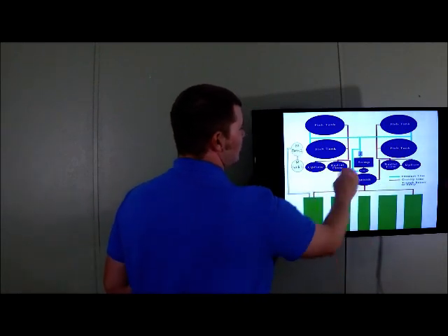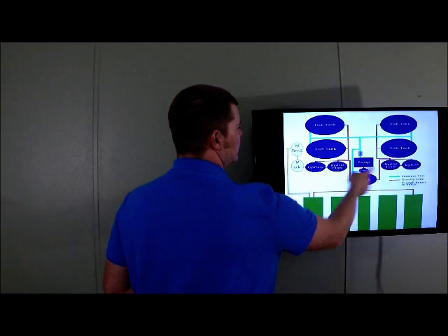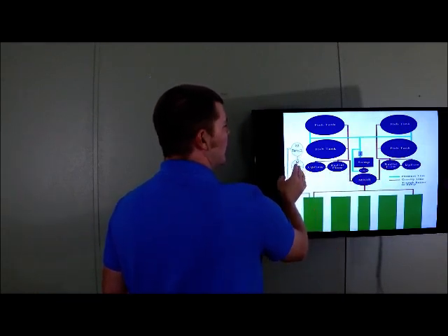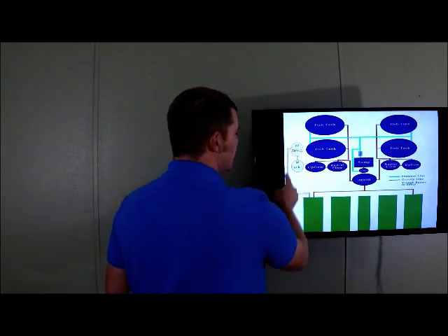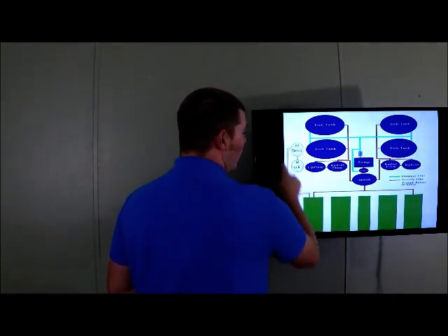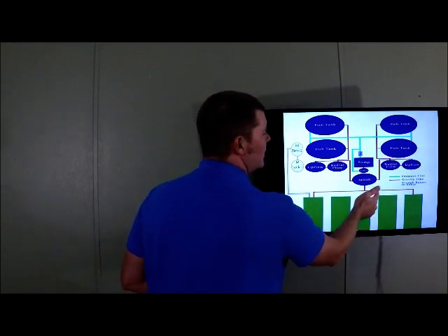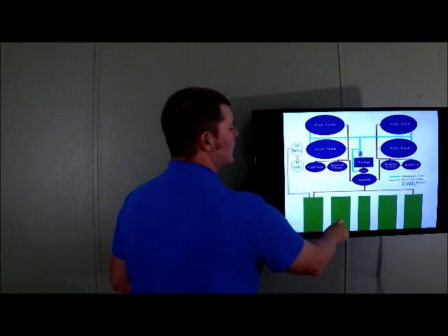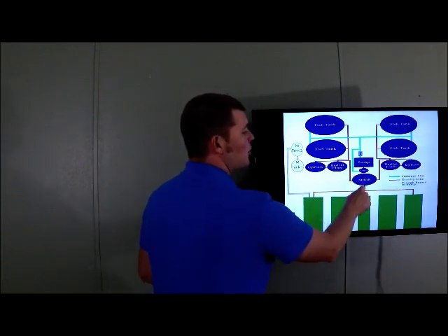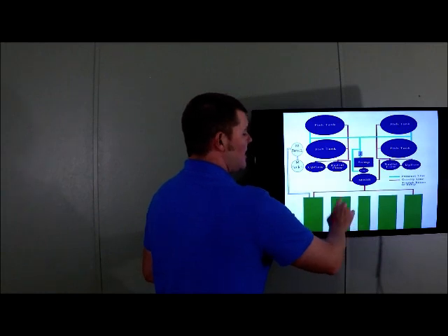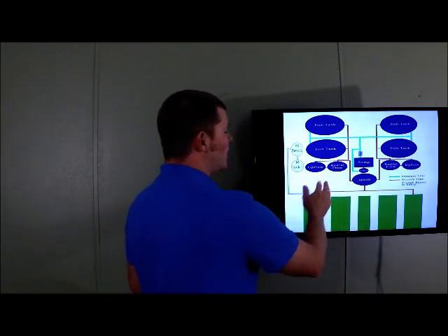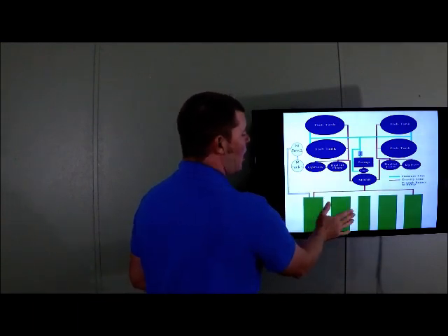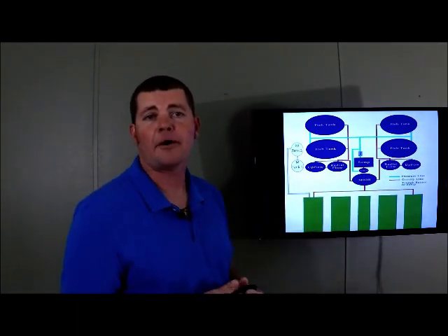This is being topped off when we empty our waste flow out of the solids filters. They go into the mineralization tank. The broken down water is sent to stage 2, and then out to the hydroponic troughs. One way, it never returns. This line, nothing ever returns. That's a closed line, so one way water goes here. If we need more water, we can open this valve and allow water in. If we need less water, where we still need the nutrients coming in, but this already has too much water in it, then we need to evaporate the water out of there.